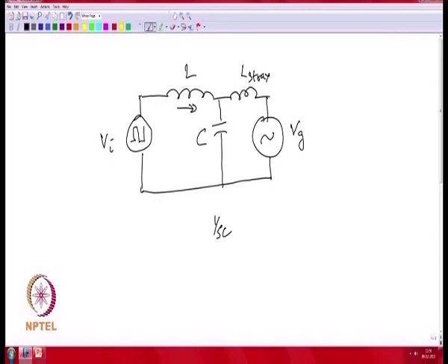It could be of the lines, the transformers, etc., going back to the grid, in which case this reduces to a LCL filter. So, this is actually an LCL filter. Practically you would end up with a LCL filter even if you just connect the C, but having in the LCL filter where one of the dominant impedances is governed by a stray parameter is not a great idea,